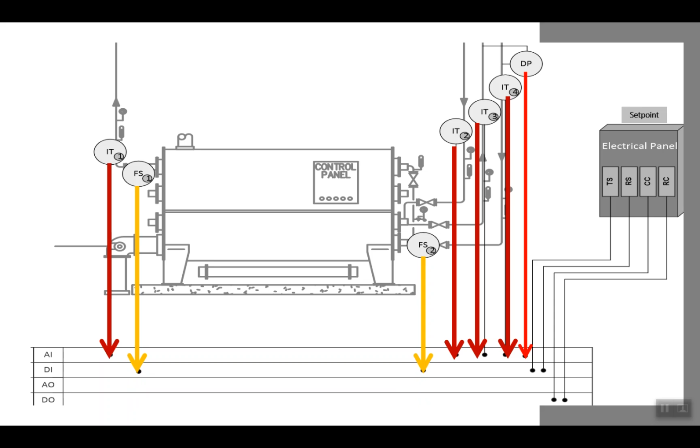Also, at the input of the condenser and the output of the evaporator, we need a flow switch. Why? In the condenser, we should make sure that the water is coming in from the cooling tower, and in the evaporator, to avoid any ice situation. If ice is forming, the chiller should be switched off. So we need a flow switch there also.